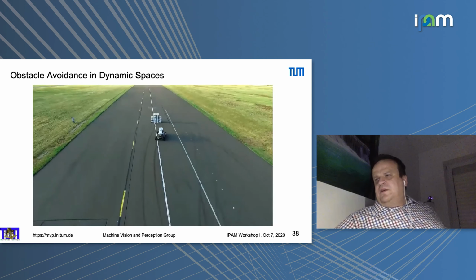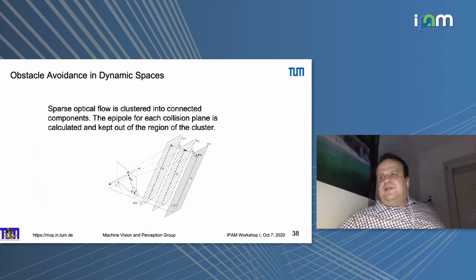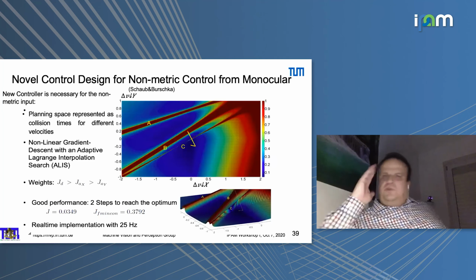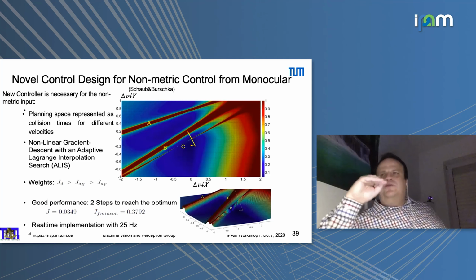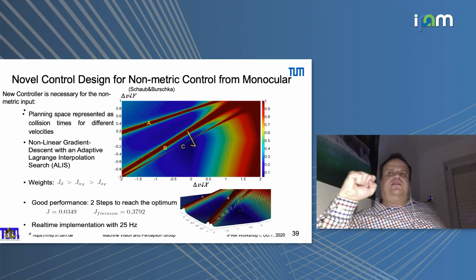Here, the system is using one monocular camera, not calibrated, and it's avoiding obstacles, static or dynamic. So to prioritize things in an environment, I can use this system without any calibration, which means if the system gets some shock during a collision, the system will still recover, because even if the focal length changes, the system will adapt to it.